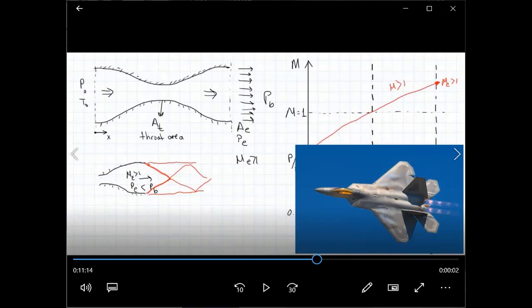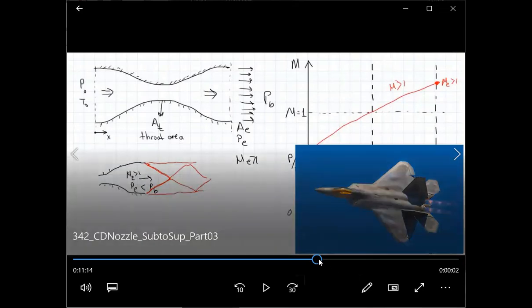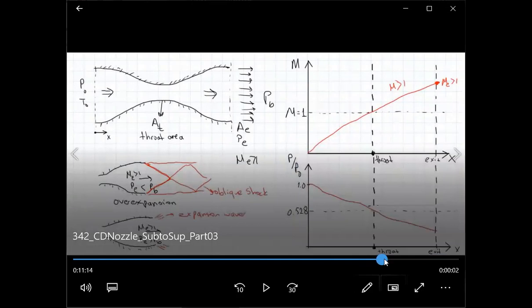And let's say you launched your rocket, and as you go up in the atmosphere to higher and higher altitudes, of course, atmospheric pressure outside your rocket very quickly drops. So that PB very quickly drops, and at some point you will end up with the second scenario. The second scenario means an underexpanded nozzle operation, where your P exit will be larger than your PB.